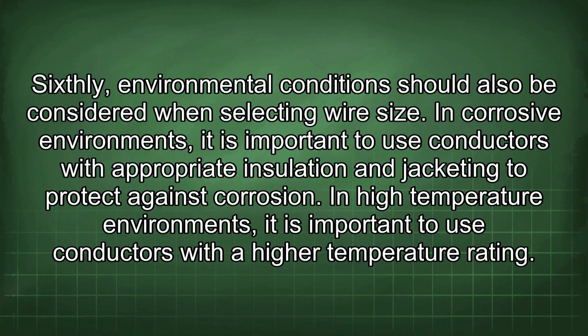Sixthly, environmental conditions should also be considered when selecting wire size. In corrosive environments, it is important to use conductors with appropriate insulation and jacketing to protect against corrosion. In high-temperature environments, it is important to use conductors with a high temperature rating.